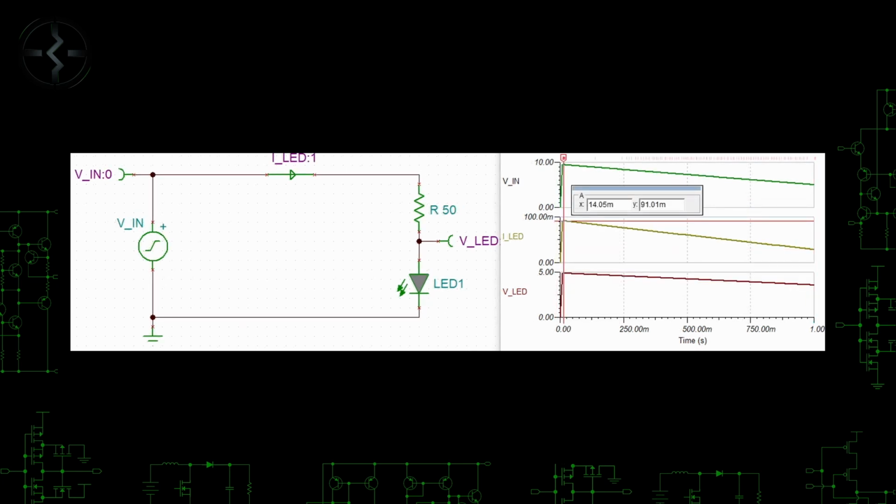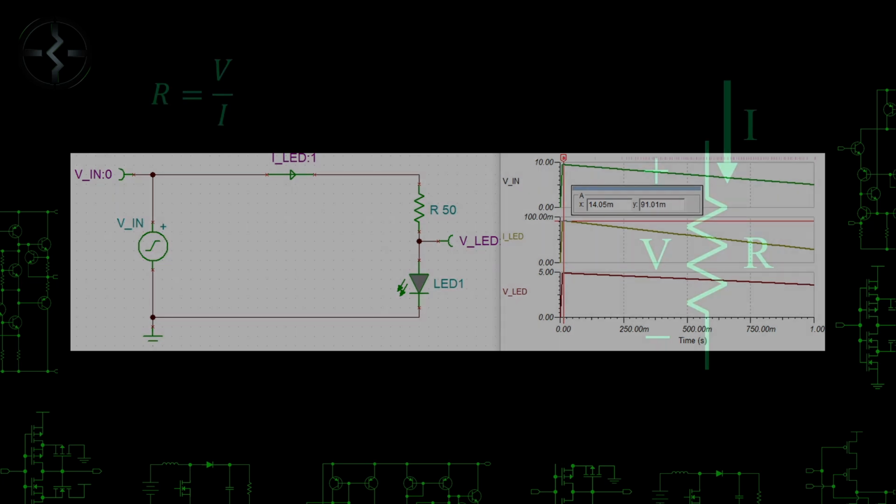Switching to a 50 ohm resistor, the current at full voltage is much higher, well beyond the absolute maximum rating of 25 milliamps in the datasheet. It eventually gets down to about 20 milliamps, but this is definitely not the solution we want. I wouldn't ever want to run a device beyond the absolute maximum ratings in the datasheet. What we can do in this situation is adjust our current requirement at the full voltage to be a bit higher than what we want, and then see how long we can stay above 20 milliamps.